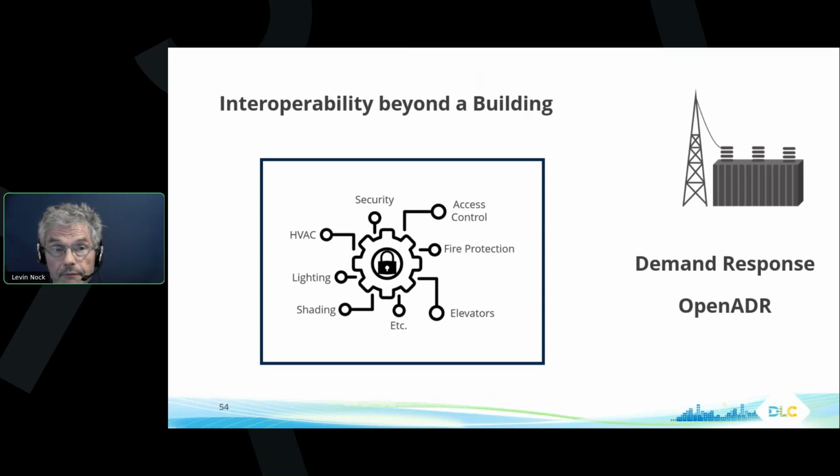Some NLC systems can respond directly to OpenADR signals from a utility website, which is a common protocol for how utilities send out signals about their demand response programs, while other NLC systems can respond to demand response signals from the utility through a building automation system, relayed by BACnet or dry contact. This capability for a lighting system to pay attention to demand response signals is important for future-proofing as the grid modernizes, in order for buildings to avoid high demand charges.